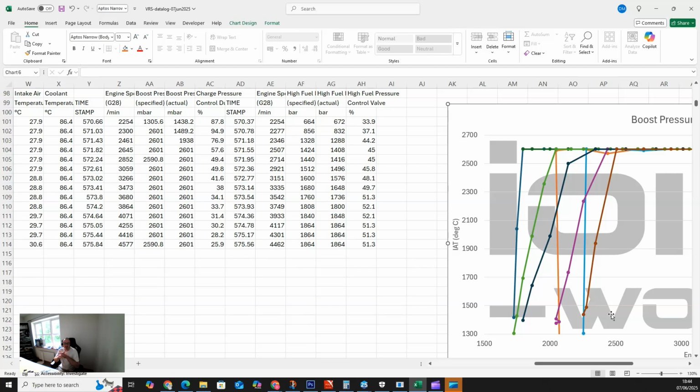So I would say in those scenarios, you might say, okay, I am hitting really high oil temps. I need to look at external oil coolers. I'm hitting high oil or coolant temps here. I maybe need to look at an alloy rad setup, or in some cases, you might need to look at a thermostat that opens slightly lower as well, just to give the system a little bit more of a chance.